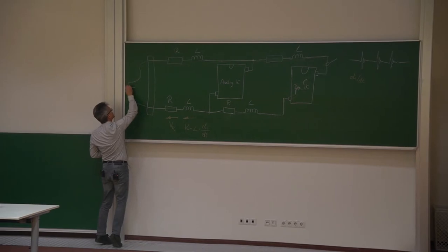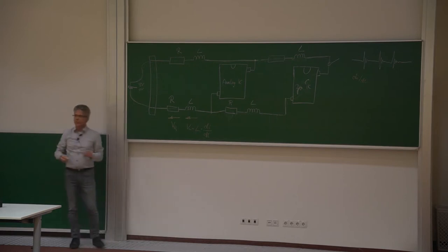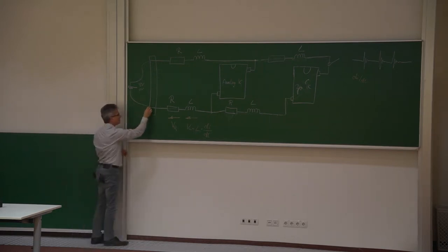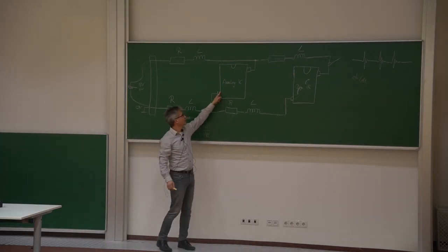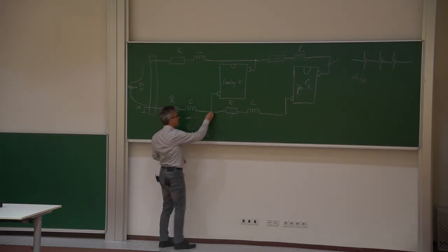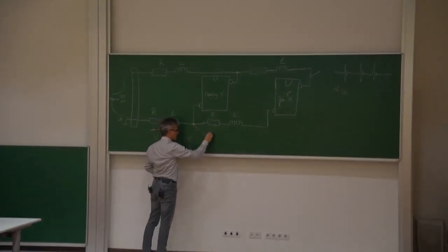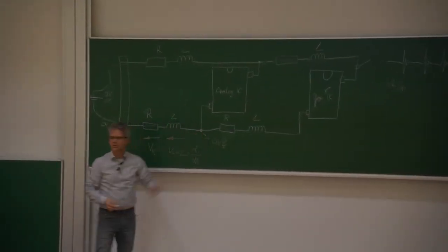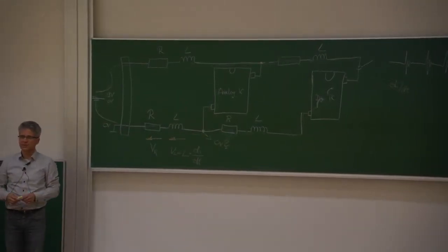This is our battery. So here at the plus pole we have whatever, 9 volt. Here at the minus pole we have our 0 volt reference. So this is our ground. Here we assume 0 volt. This is our analog IC that is connected by the ground pin to the ground of our printed circuit board. But is this point here also 0 volt, as it should be? Hope you agree. Definitely not.